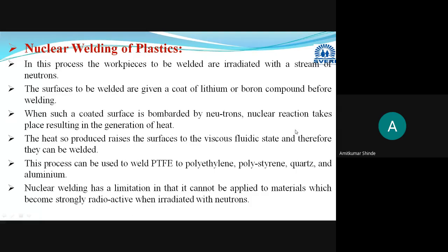A nuclear reaction will occur between the neutrons and the elements present in the coating, lithium or boron, and heat is generated on the surface itself. That surface will start melting, and with the application of some pressure it will get welded, or the desired joint is obtained. In this way, nuclear welding of plastic is performed.